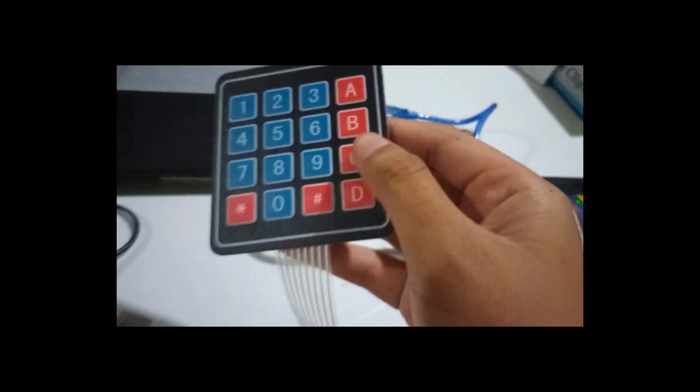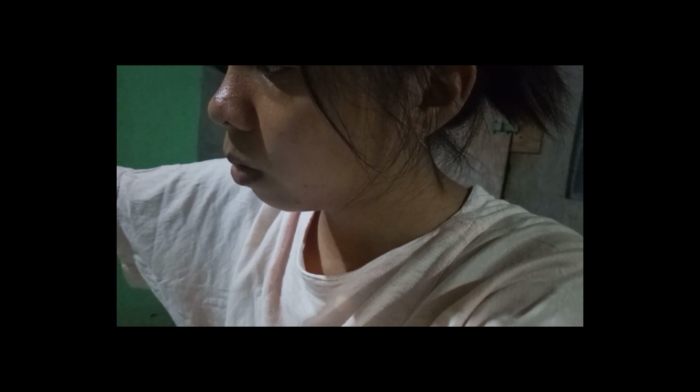So we're all set. We have connected the keypad and the LEDs and the Arduino Mega to the laptop with the code in the IDE software. So we're gonna upload this. I already verified my code. So please verify your code before you upload it to your Arduino Mega, so you can protect your Arduino and check first what errors are in your syntax.